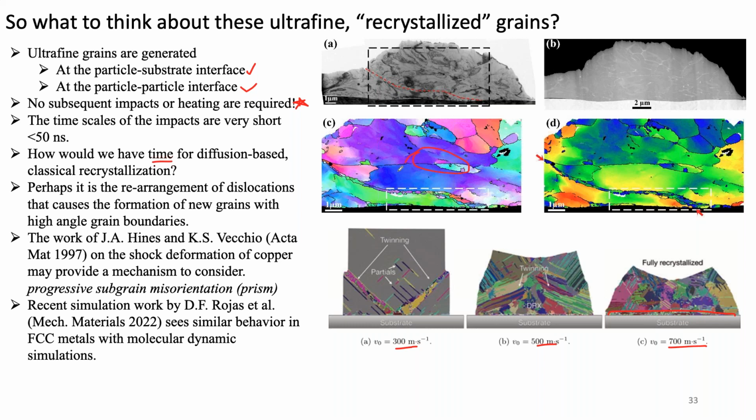So ironically, early on, cold spray was very attractive in part because of its limited thermal heat input. Now you're actually increasing the thermal heat input. It's really all about control. And one of the biggest areas we're actively working on in my group is understanding and controlling the heat transfer process during laser assisted cold spray, because you can in fact get carried away for sure.